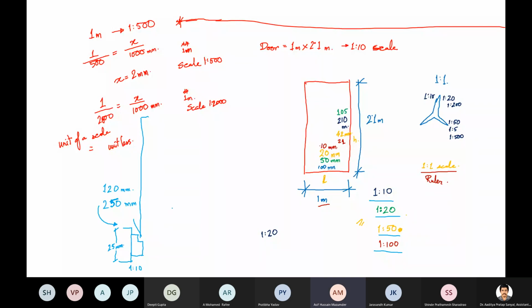Like below the name of the particular drawing? Say, probably this is the swing door, and at this level you can mention it. Probably the font size would be much smaller than how you have written this swing door. If this is 5 mm on a scale of 1:1, then this one would be written at 3 mm.